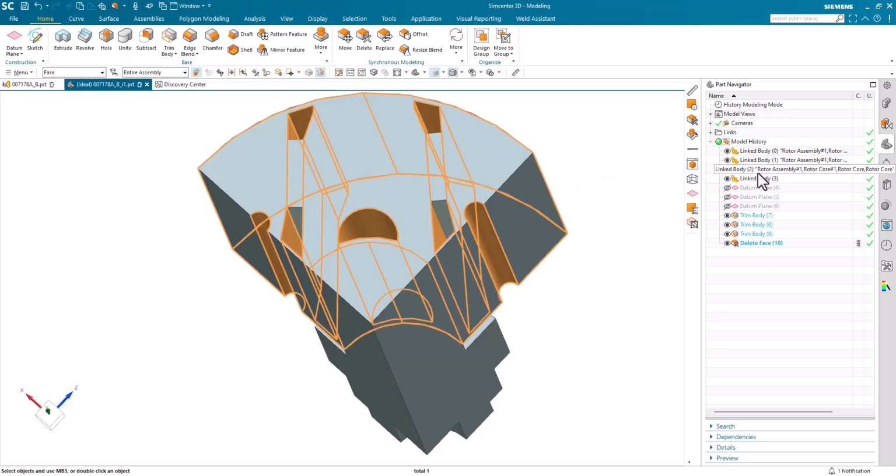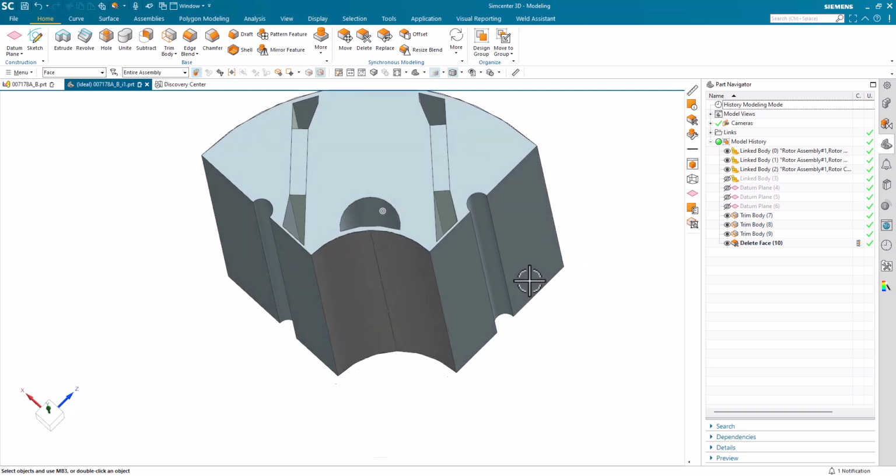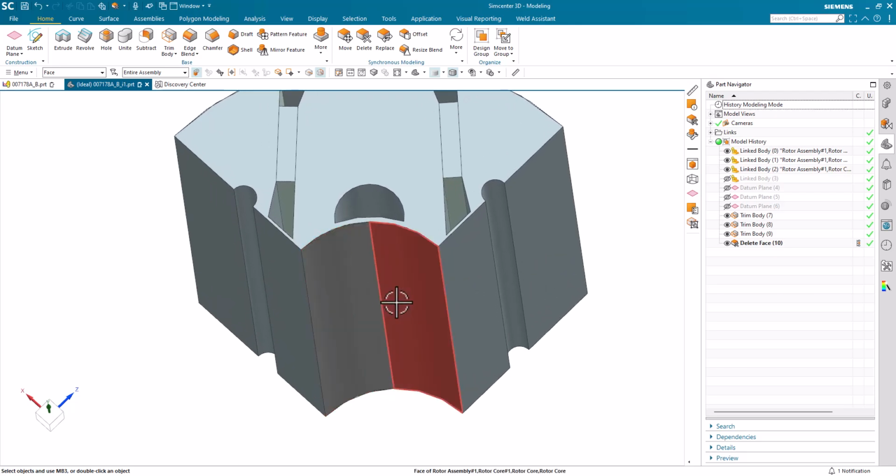One other thing I want to do is, I know from operating on this, if I hide this body, no, I actually want that body shown. I want to hide the shaft. So this face combination, I don't need this, and then for meshing, I actually want these 2 edges to be one, both on the shaft and on the rotor.